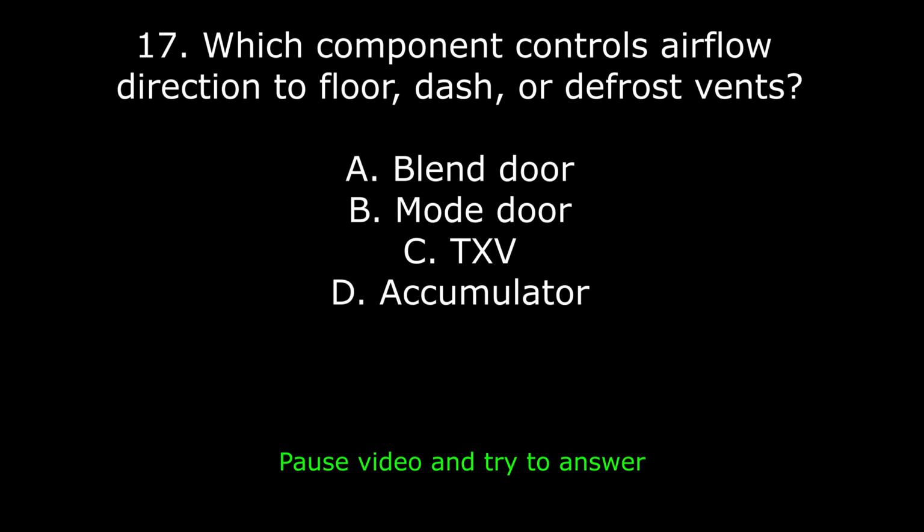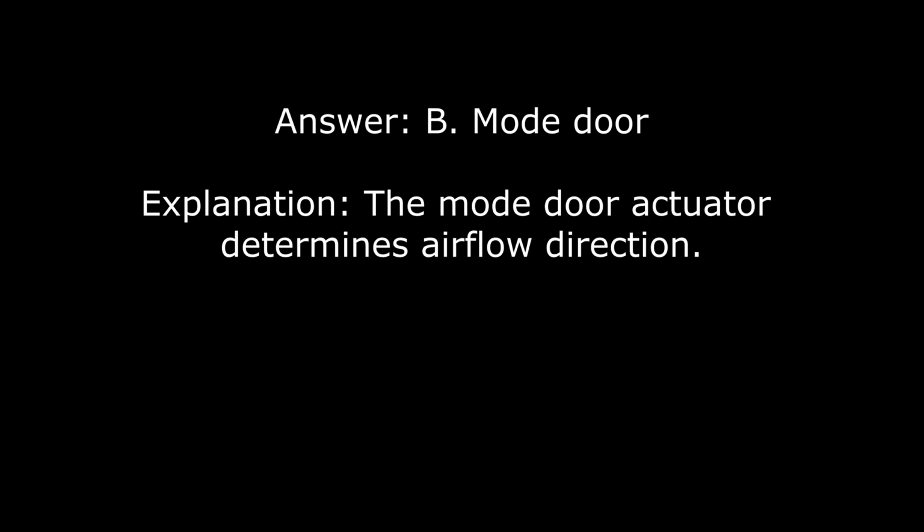17. Which component controls airflow direction to floor, dash, or defrost vents? A. Blend door. B. Mode door. C. TXV. D. Accumulator. Answer: B. Mode door. Explanation: the mode door actuator determines airflow direction.